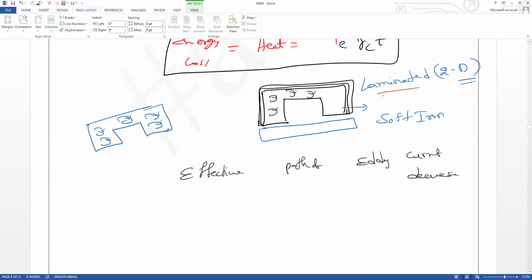So these eddy currents will decrease. How? We have to minimize the eddy currents. So how to minimize the eddy currents? Make the three-dimensional block into plates, laminated cores, along with the insulating liquid in between them, which is what we call transformer oil. So the laminated core material has insulation between the plates, like an air gap, with insulating liquid in between that we have to pour.